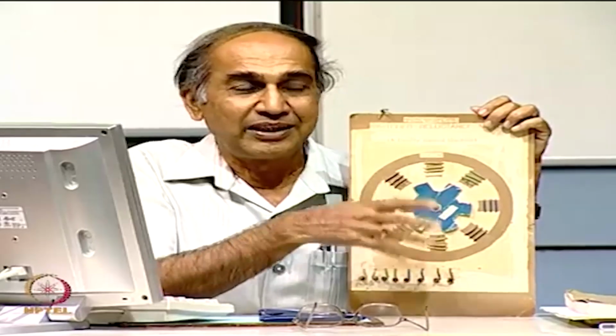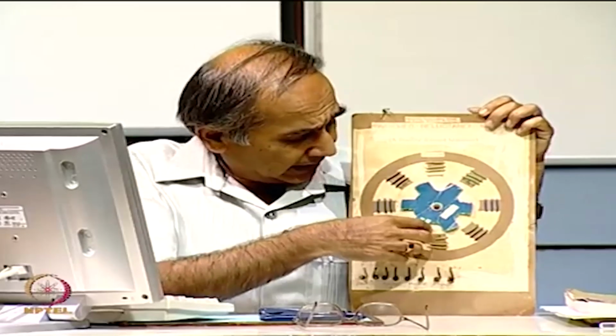So, you need to have a processor, and this machine cannot work without a controller, whereas a DC machine can just be put to the supply. You can't put this one to the supply. If you put it to the supply, nothing will happen except the winding will get burnt. Therefore, you need a black box or a controller between this and the supply. So, these are the broad things I have explained through this model. I assume that you have learnt everything about switched reluctance motors.